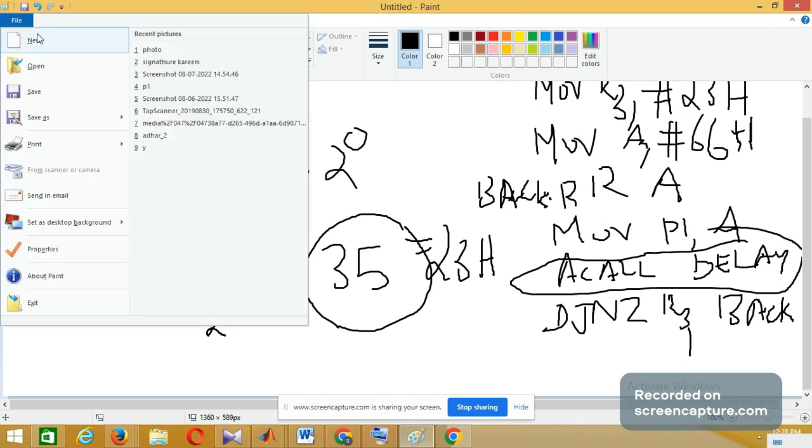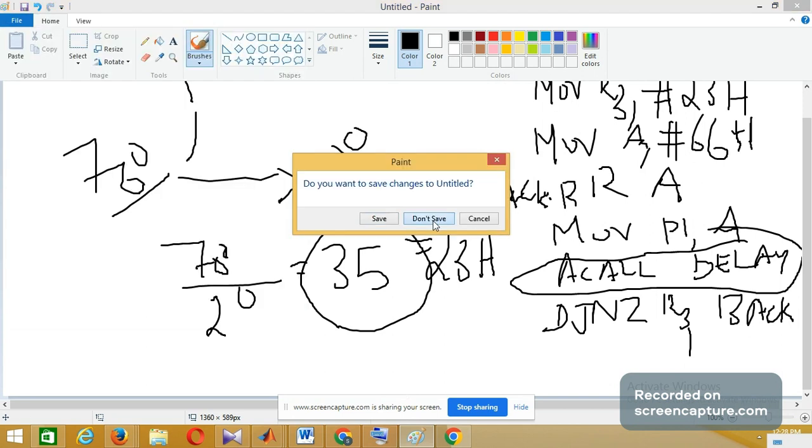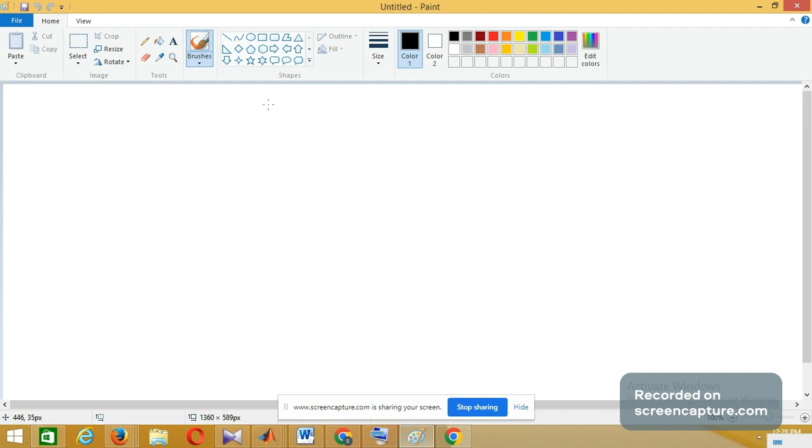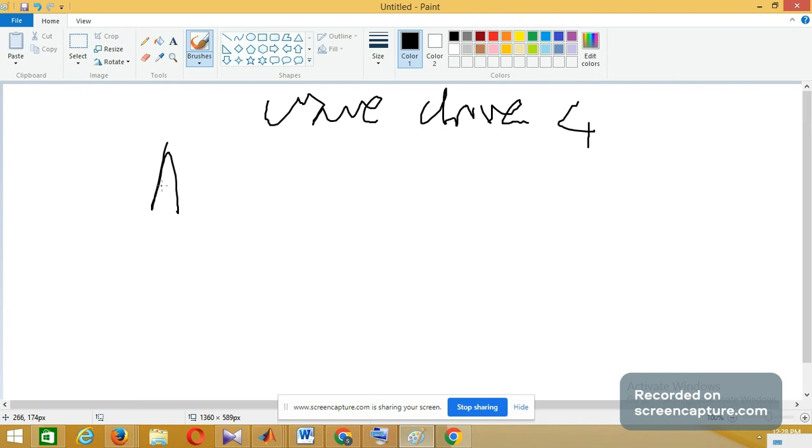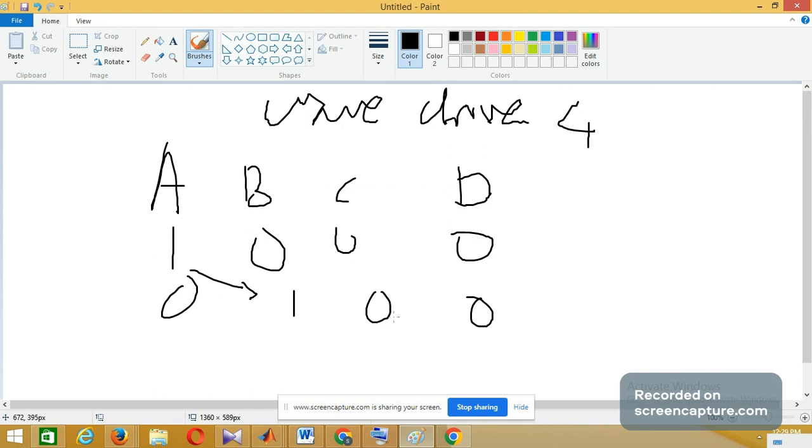Now there is another way you can control the stepper motor, which is called the four-step wave drive sequence. In that case, what you are supposed to do is, at a time you make only one bit 1. So first give 1 0 0 0. Next you have to give 0 1 0 0. Next 0 0 1 0, 0 0 0 1. If you move like this, to the right side, it is the clockwise direction; left shift will be the anti-clockwise direction.